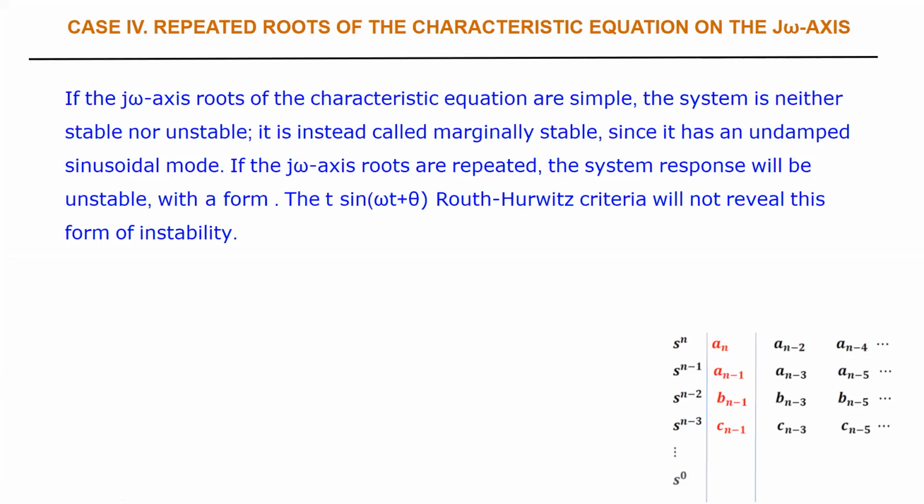What we were doing, we were using Routh-Hurwitz to test if a system is stable or unstable. To summarize what we have done so far, the first thing we'll do, we look into the characteristic equation. In the characteristic equation, if there is one term missing or there is a sign change, we can conclude immediately that the system is unstable, and we stop. We will answer that if the question is whether the system is stable or unstable. We'll say, okay, the system is unstable.